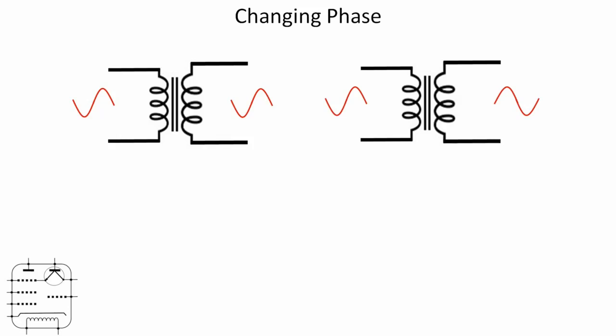Now it doesn't appear a great deal in circuit diagrams, but you may on occasion have seen a pair of black dots, like so there on the left hand side, and they are to indicate the way the transformer should be wired up, because it matters that the phase remains the same before and after it's passed through the component. Whereas on occasion we actually want the converse to happen, and so you might see something like that, with the dot on the top left on one side and bottom right on the other.